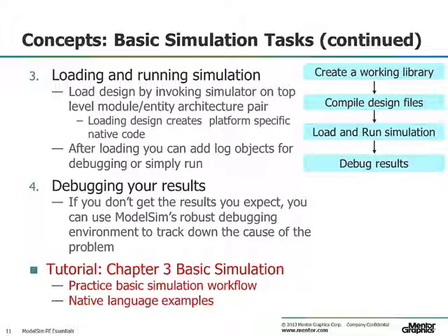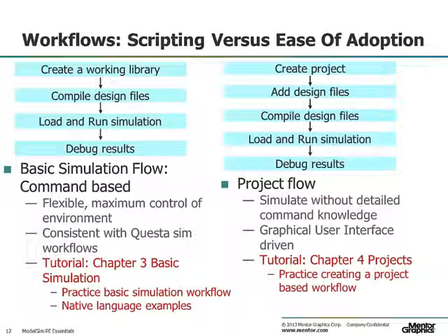Of course, ModelSim has very many options for debugging. We will introduce the rich debug environment, but now we want you to practice the basic simulation flow with Chapter 3 of the tutorial. Optionally, you can review the project flow that I will introduce next, if you would rather drive simulation via the graphical interface. So let's talk about the two workflows, basic simulation flow and the project flow.